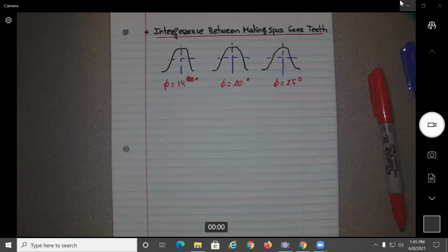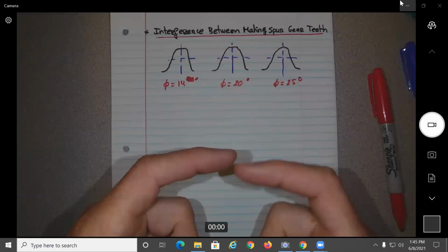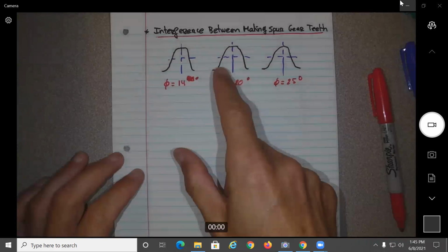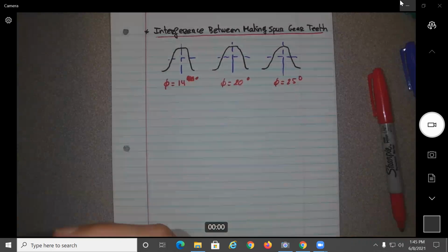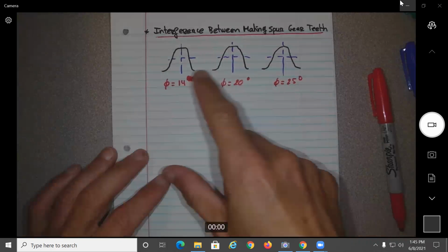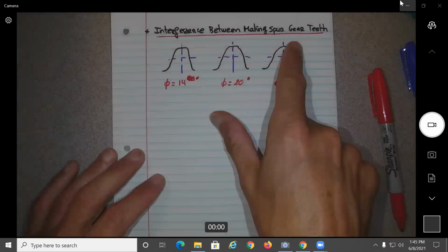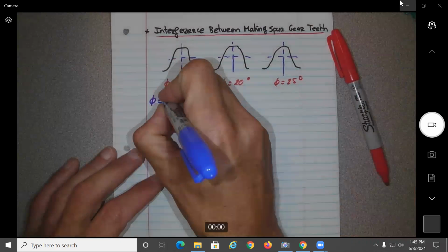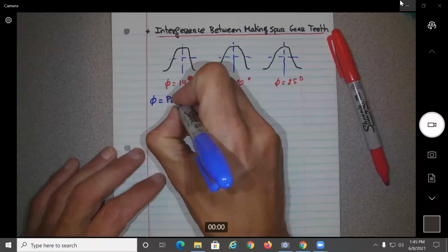If they were the same diameter, it should be a relation 1-to-1, no? Okay, but since they have different diameters, in order for them to be optimal, the number of teeth you can have in a certain gear will depend on the angle of this phi, which is what was defined as the pressure angle.